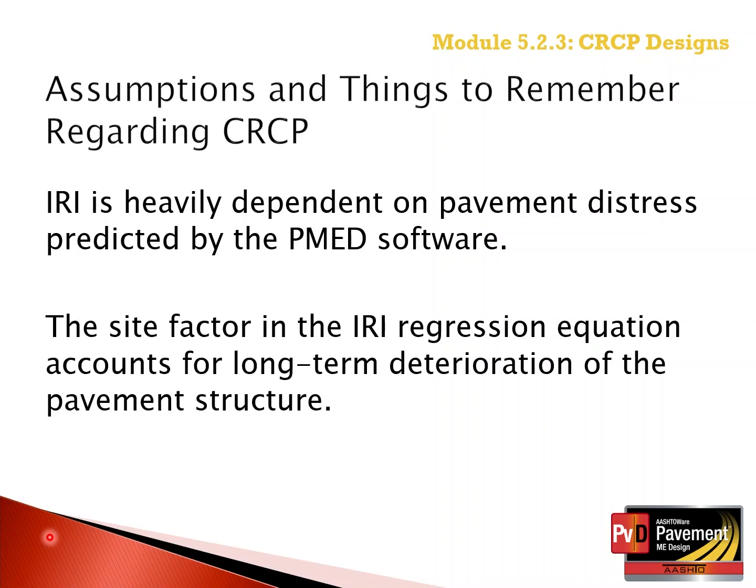IRI is heavily dependent on pavement distress. For CRCP, it is heavily dependent on punch-outs, as well as the site factor for some climates and some soil combinations. Removing and replacing problem soils, such as highly frost-susceptible soils and highly expansive soils, can reduce the impact of the site factor on the increase in IRI over time.